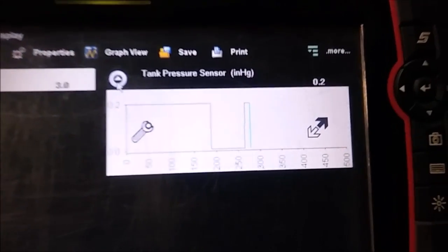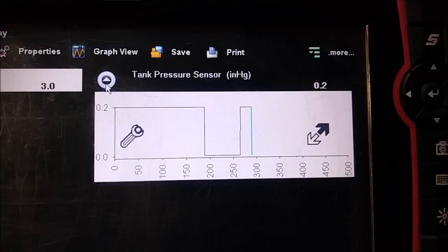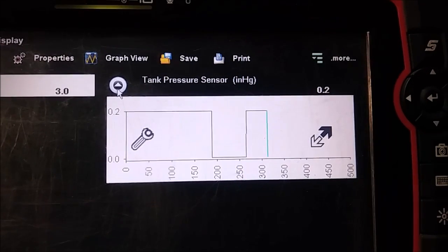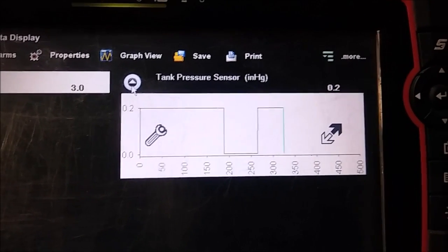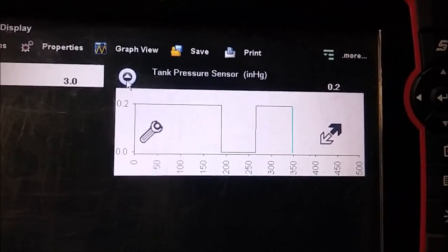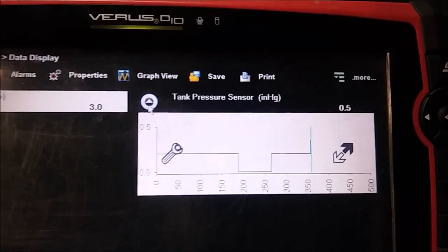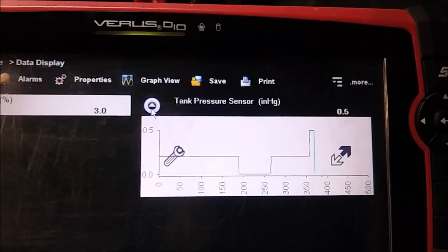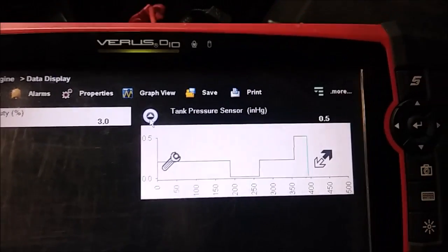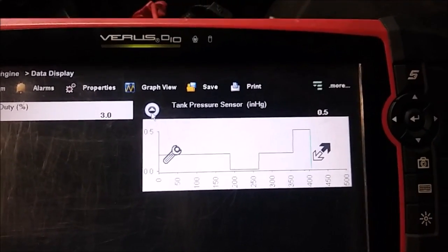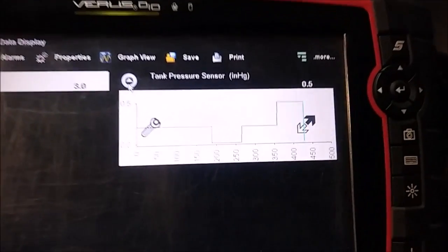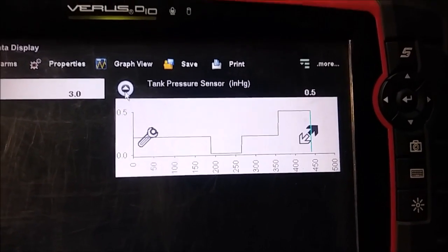and we're just watching this number. We see we jump back up to this 0.2. Not really seeing any other response other than that. Again, this could indicate a sensor issue or potentially a humongous catastrophic leak in the EVAP system. The code we had in memory was for a small leak, so let's just keep that in mind. We just saw it jump up to 0.5 there. Definitely not a very clean operation on this sensor. I'm not sure if that's normal for this particular vehicle or for the scan data I'm using for it or not, but it's reacting to this.